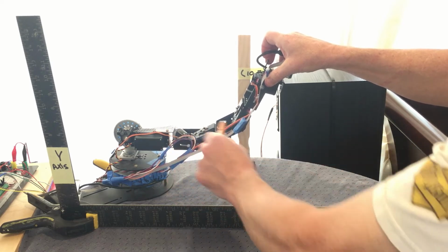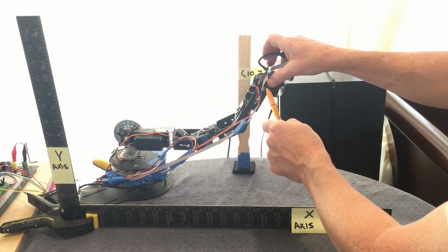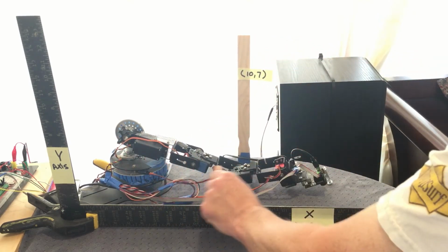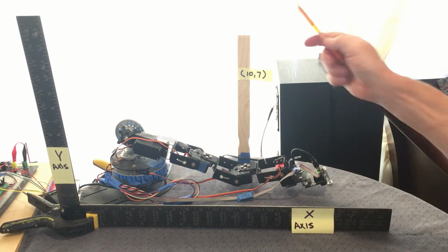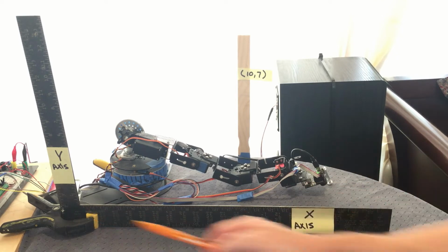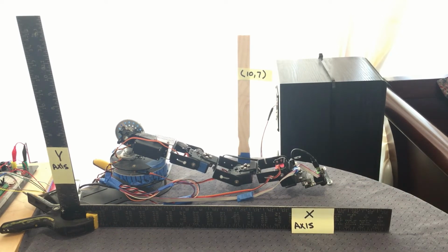And the thing is, these are all unknowns, and the only knowns are the length of your servo arms from joint to joint, the target location, and your starting location, which is 0, 0. And given that, you form triangles to go backwards to your origin and calculate the required angles for each of the servos, or the angles of the triangle. And that's basically it. So let me show you on paper how that all works out.